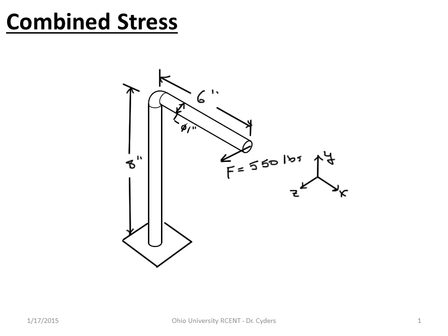It's just this idea that we have a bent bar, and let's say, just for clarity right now, that this 8-inch section is aligned with the y-axis, this 6-inch section is aligned with the x-axis, and our force, 550 pounds, is aligned with the z-axis, and that this bar is rigidly mounted at the bottom here. And so the question we want to answer in this presentation is, how do stresses combine at a single point?